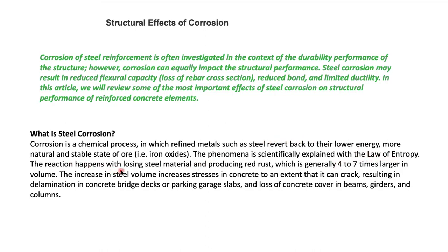The reaction happens with the loss of steel material and produces red rust, which is generally 4 to 7 times larger in volume. The increase in volume increases the stresses in the concrete in contact, causing it to crack, resulting in delamination in concrete bridge decks or parking slabs, and loss of concrete cover in beams, girders, and columns.